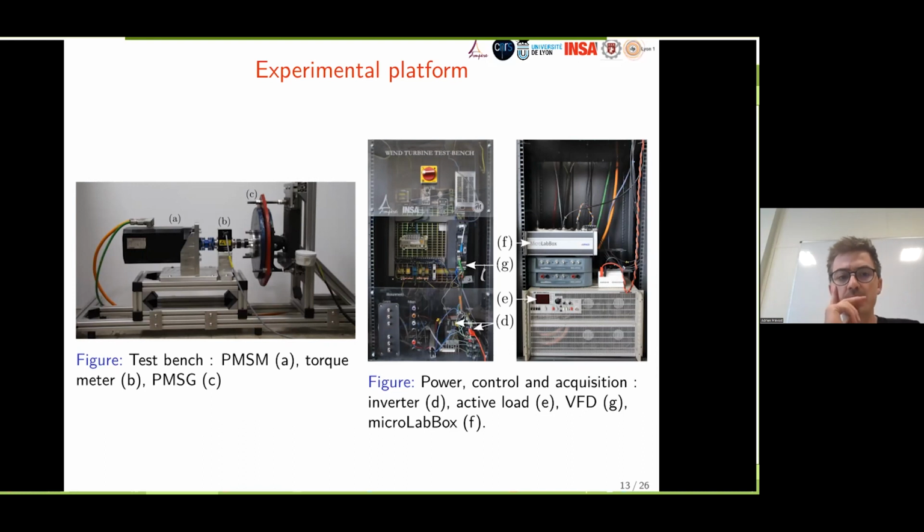And for your second question, with this emulator, we were able to inject some turbulent wind. We did not share this work today, but if you have a look at the paper about the emulator, we were able to reproduce the turbulent torque that is applied on the blades thanks to the emulator. And we use the TurbSim from the NREL to do that.